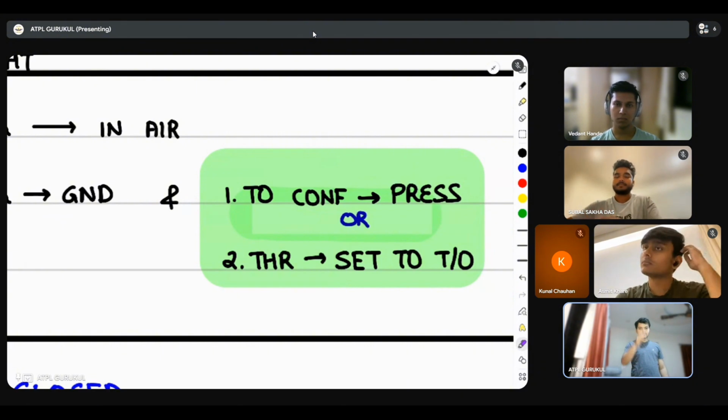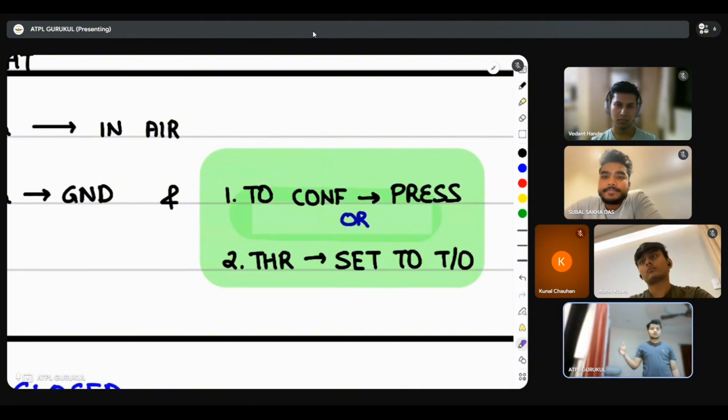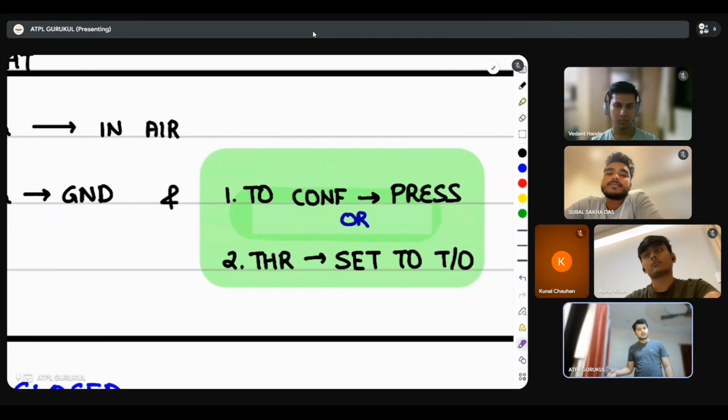Then you go all the way down, ATC, transponder panel as required, communications as required, and then you go to your mode selector, and then you go to your radar and predictive windshear. Once you go there and you press the takeoff config test push button, you can literally hear the sound inside the cockpit change from a closed configuration to an open configuration, from an open configuration to a closed configuration.